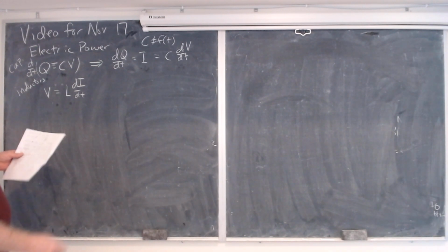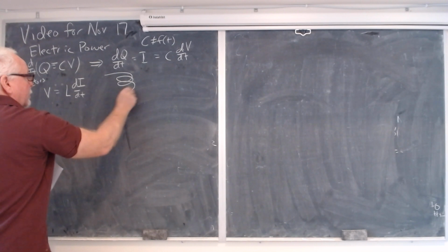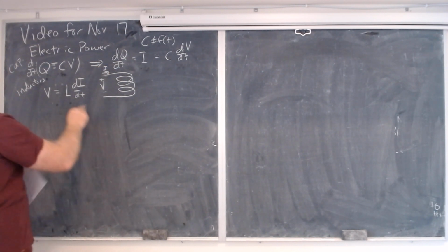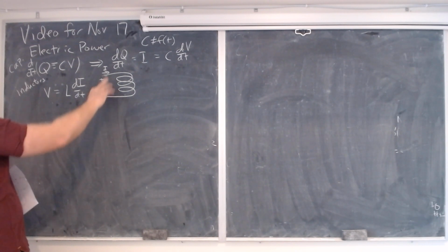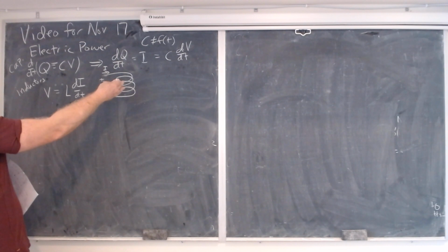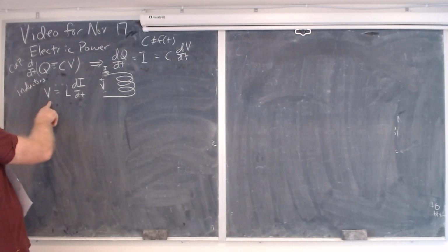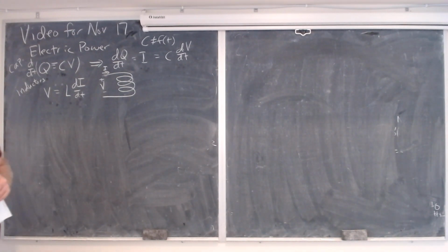Now, what we know about an inductor is that it's a coil. So if I have a voltage and a current, the current voltage relationship is that. And it makes perfect sense, right? Because if it is just a coil like that, if nothing is time varying, a coil is just a wire. And so if there's no rate of change of current with respect to time, voltage is going to be zero because it's just a short circuit until you start time varying.